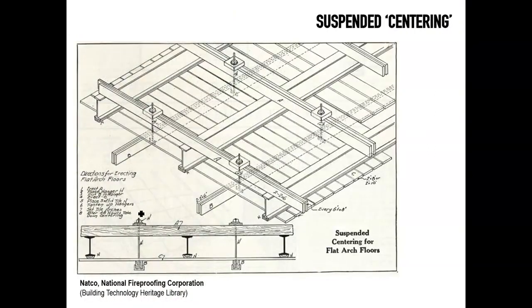Well, there was quite a clever approach that, of course, first the steel will be in place, like all the skeleton system will come up first, and then a number of joists will be run perpendicular, so you can see the steel beams running first in these positions.